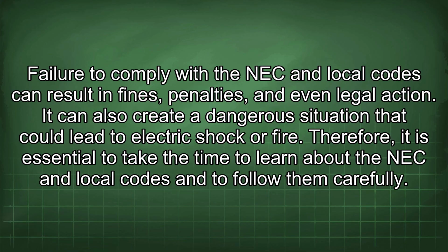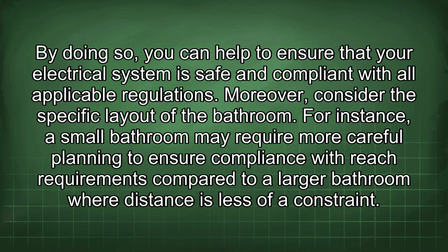Therefore, it is essential to take the time to learn about the NEC and local codes and to follow them carefully. By doing so, you can help to ensure that your electrical system is safe and compliant with all applicable regulations. Moreover, consider the specific layout of the bathroom. For instance, a small bathroom may require more careful planning to ensure compliance with reach requirements compared to a larger bathroom where distance is less of a constraint.